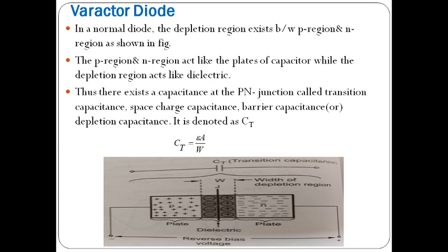First, we will discuss the varactor diode. This varactor diode is also called varicap or tuning or voltage variable capacitor diode. It is a junction diode with a small impurity dose at its junction, which has a useful junction capacitance or transition capacitance, which is varied with the voltage.